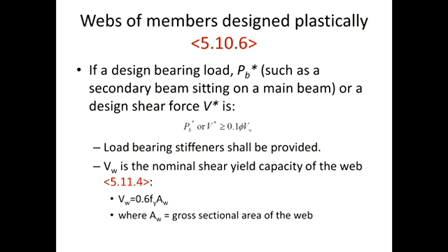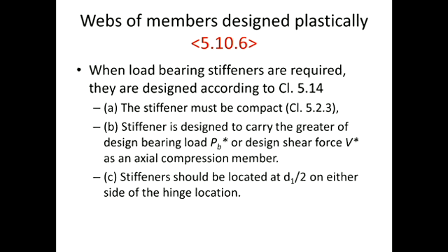If we have this condition, it means that we have to design for load-bearing stiffeners. We have to provide load-bearing stiffeners at those locations where the plastic hinges are going to form. This is just to ensure that the plastic hinges can be formed, and then in the design of the stiffeners, we have to ensure that the stiffener is compact and able to carry that load.